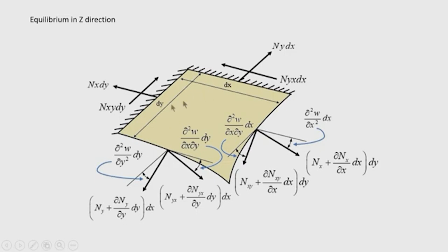So, in a similar fashion, now we can calculate the change of angle, that is the slope, because here we clamped it. So, del square w by del y square into dy. The intention of clamping the edges here is only to get the change of slope as something minus 0, for convenience of calculation, no other purpose. Okay. So, del square w by del y square into dy is the slope here, that is the angle.